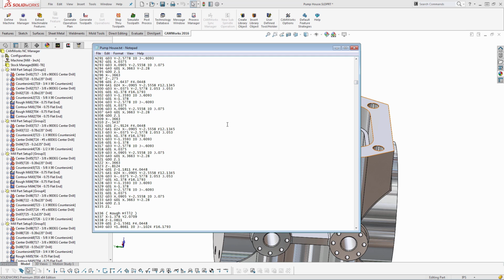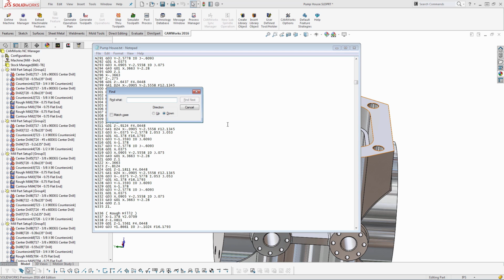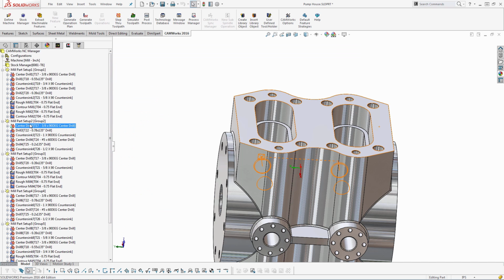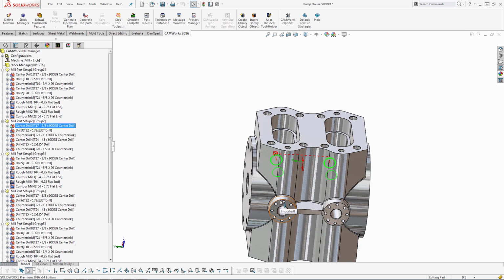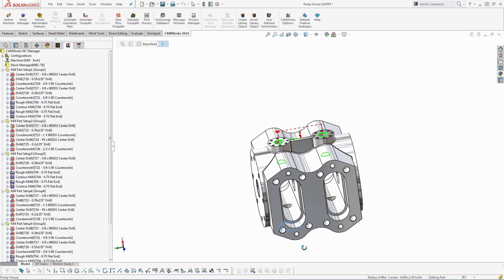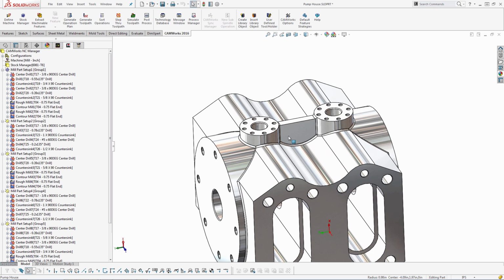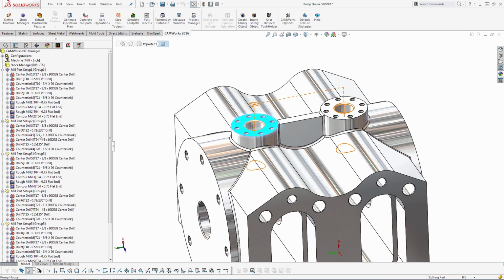And if I just do a search here, A, we see an A0 on center drill 3, which is at the beginning of setup 0. So our first setup from this direction was minus 90. Remember, I set this as my 0 plane. So when we got to setup 2, we went to A0. So there's 4-axis indexing. You're programming the part essentially the same. You're just automating the moves between the rotary axes.